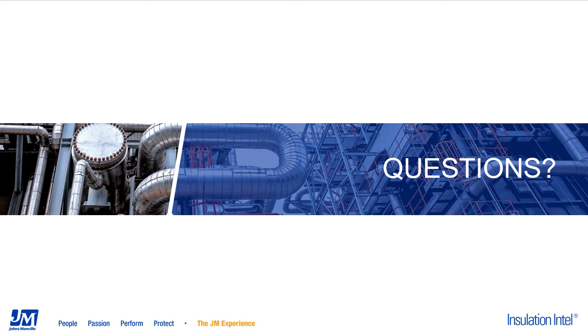As far as the mineral wool itself is concerned, I'm not sure of anything off the shelf. You would have to look at sizing your fittings accordingly to accommodate the topography that you would see in that type of fitting. And typically you'd have to stuff any gaps with a loose fill material, because you don't want to create air gap cavities within the system. So I'm not aware of anything off the shelf that we would have prefabricated to accommodate that.